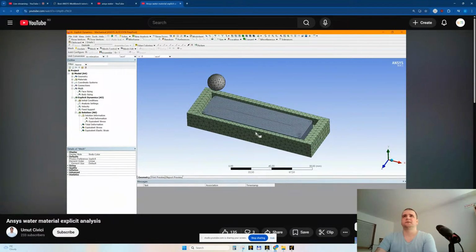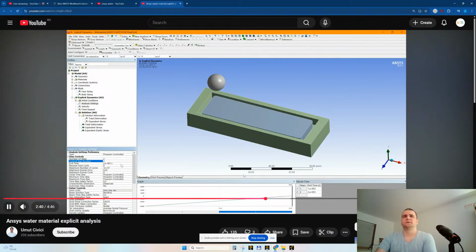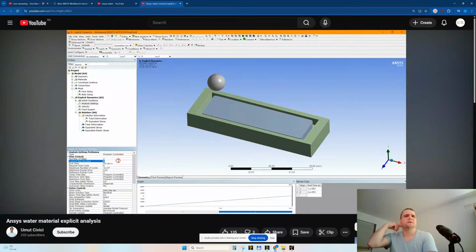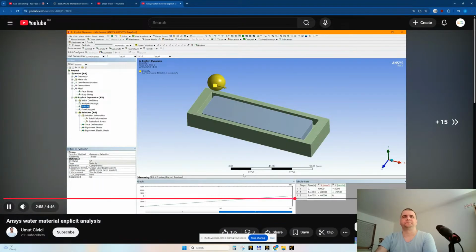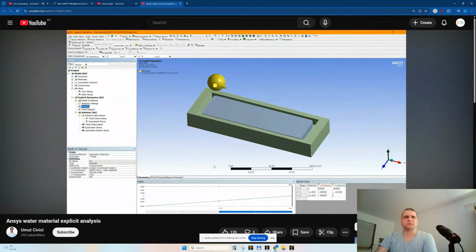All right, meshing. Yeah, it's a fine mesh. So here, 2e minus 3, 0.25 maximum energy error. Why did you put that value? Why? Default is 0.1. Why? All right. Speed. The speed is 40 meters per second, 130 kilometers per hour.